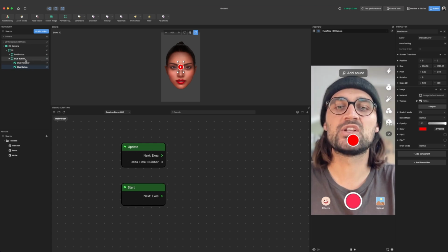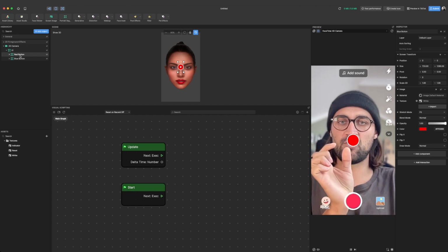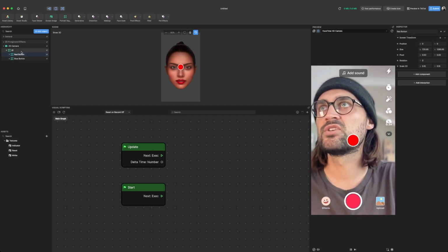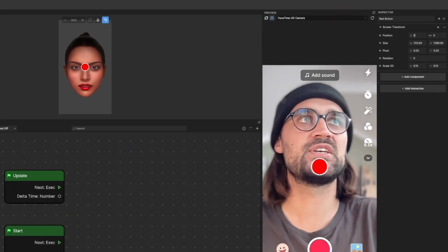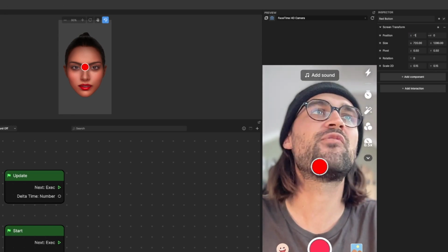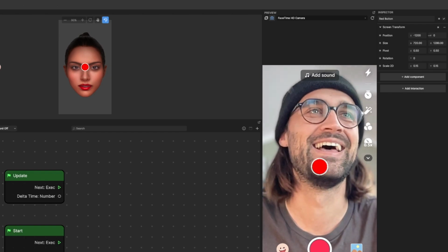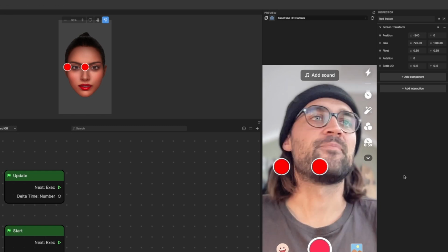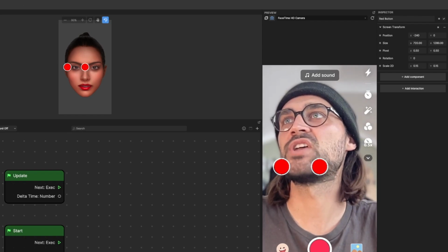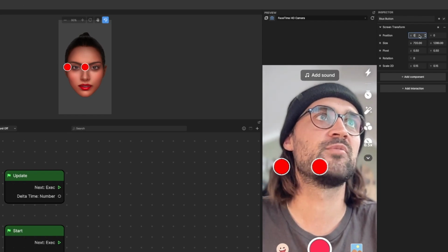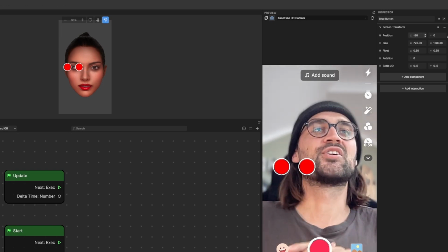So we have to change the position of our buttons. The red button has to go here and the blue one here. For the red button, just select it, the nested thing, then go to the right hand side, and here set the position of the X to -1200, and that's too much. So yeah, set it to -240. The next step is that we also change the blue button, and the blue button position will be at X -80. Yeah, -80 looks good.